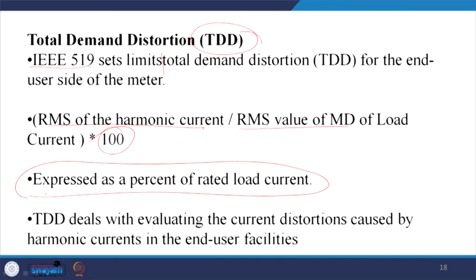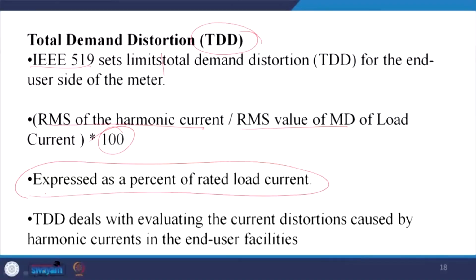If you take a 3 kVA meter, your load current is limited to around 15 ampere. If you are taking a 6 kVA meter, load current is around 30 ampere. So, these are all single phase currents with some amount of tolerance. Thereafter, after 6 kVA we generally have 3 phase meters. So, there also we have to take this into account.